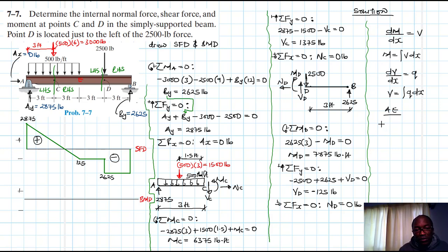So what do we have? We know that our shear is positive, so there is a slope there. There is a point where shear cuts the x-axis, where shear is equal to 0. We need to find that point. It's quite important, because it gives us the maximum moment. So let's find that point. Let's call that point x.